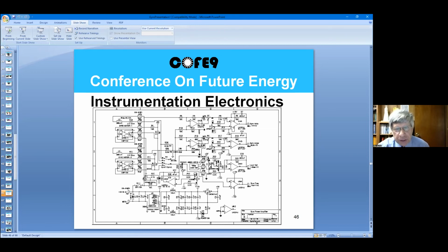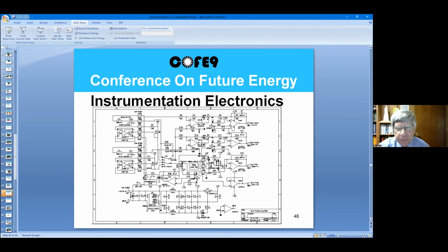That goes down to a selector switch so you can monitor left or right gyro. And then the outputs are all buffered, isolated, and scaled. You've got the voltage scaling, the current scaling, and the frequency scaling. And then the load cell is scaled over here. And they all run out to BNC or coax connectors over here that go for the scope monitoring.